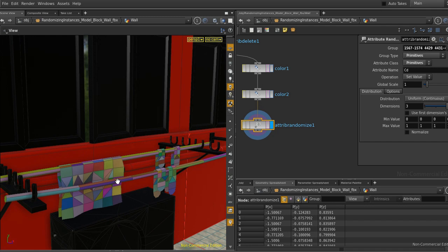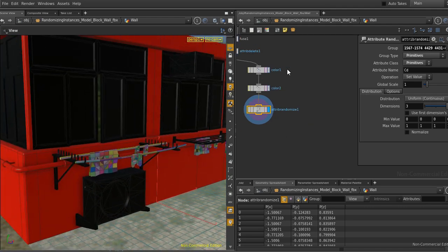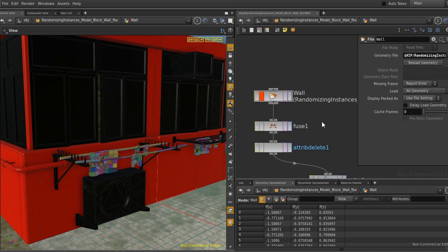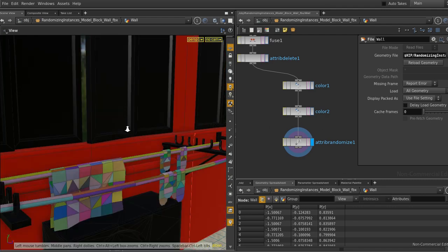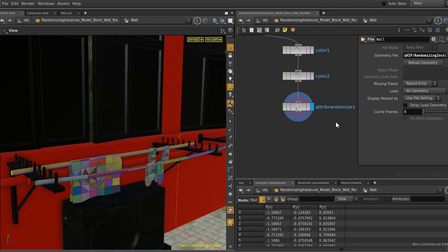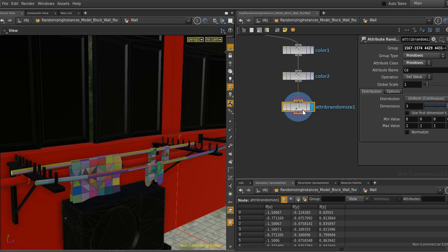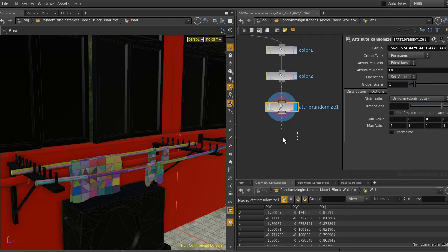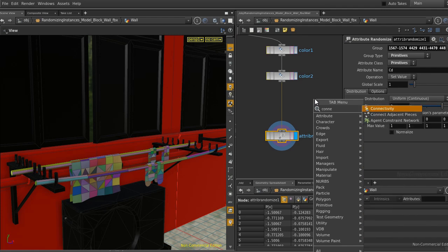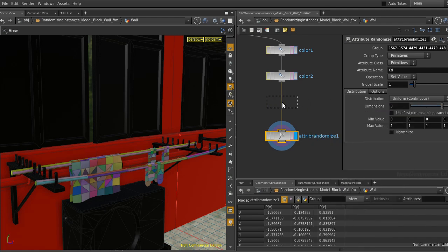Now I want it to choose a random value for the entire submesh. But this object is only a single mesh. It's not separated into objects here. I merged it all to export it to Unreal. It's completely not a problem for Houdini. I just need a connectivity node. Sub is a name for node.